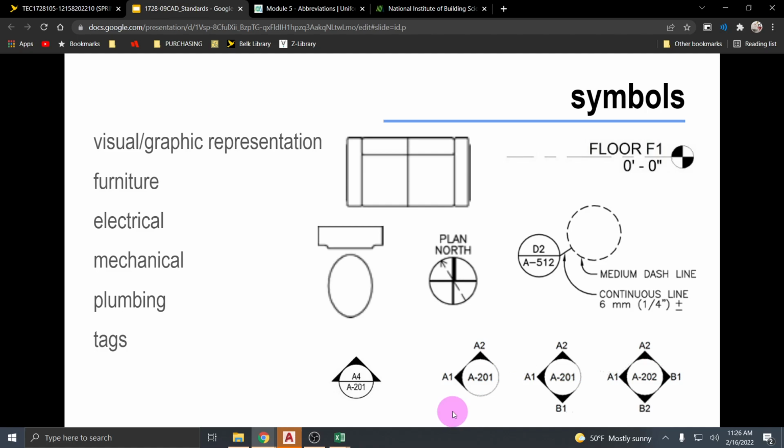And so that's what some of you did a little wonky, in that this was also just drawn incredibly awkwardly onto the circle. And I know sometimes it's really hard to get tangent lines on circles, but for some of you it came out like really pointy, and it should be a little bit more gentle than that. But then this is just telling us the sheet number to go look at and then the view identifier on that sheet. And depending on how many interior elevations are done of a single room is going to depend on how many little pointed pieces you can put on. So it can go all the way from just having a single one to all four completing a diamond on each side.